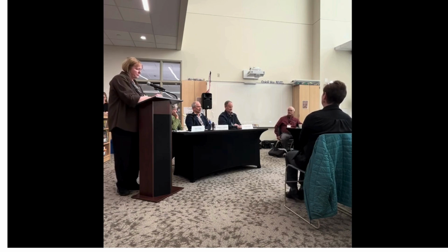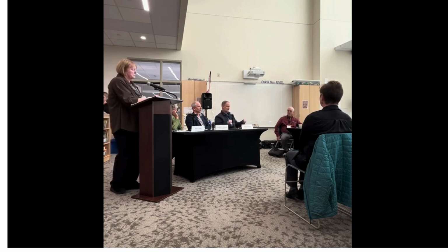We looked for a Friday where it was professional development, when nobody was in there. We got Friday, Saturday, Sunday to do the testing, and then we backed away, back to the same routine, and then had everybody looking at it and going for a week, where we could actually charge in huge tankers of glycol to push air out of the system in the geothermal, make sure that it was critically charged, go back to the pressures, testing the pressures, having the pressure report and saying, yep, it all looks the same right now, and then releasing it, and then found the leak.